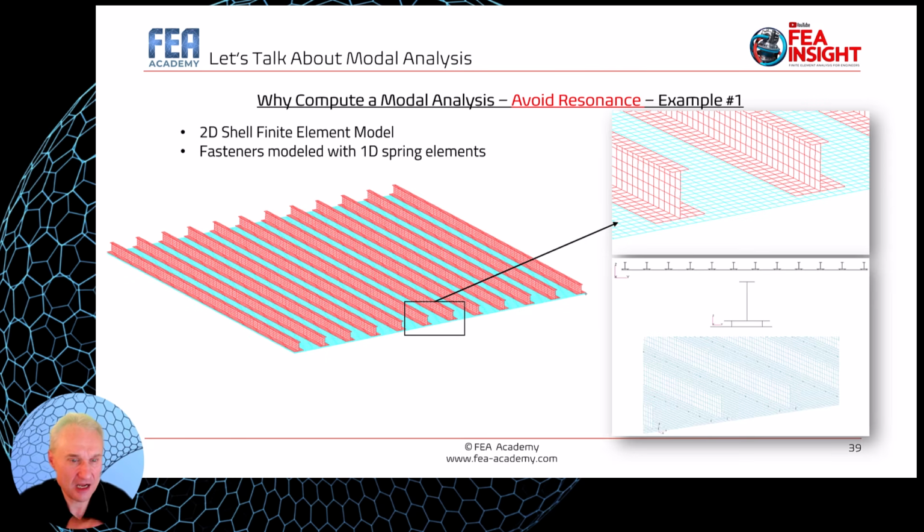First, I want to show you how you need to model the panel. Here, it is a typical stiffness panel where you have in blue the panel itself and in red the stiffeners at a certain pitch with a certain dimension. So the question is, what is the thickness of the plate? What is the height of the stiffeners? What is the pitch of the stiffeners I have to build in order to have a panel satisfying the requirement?